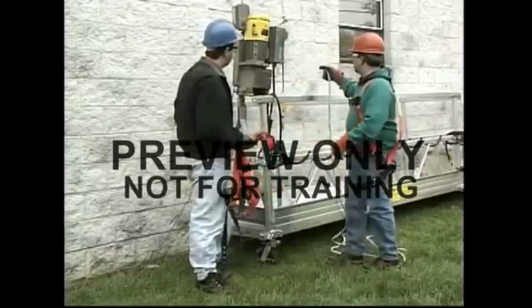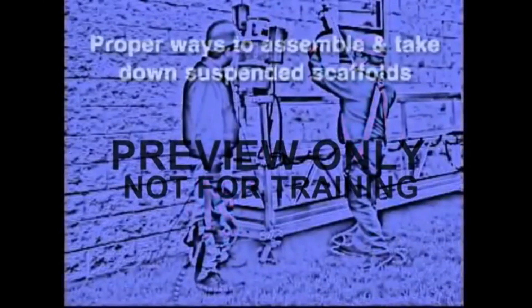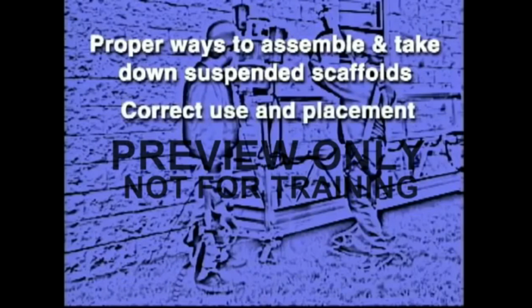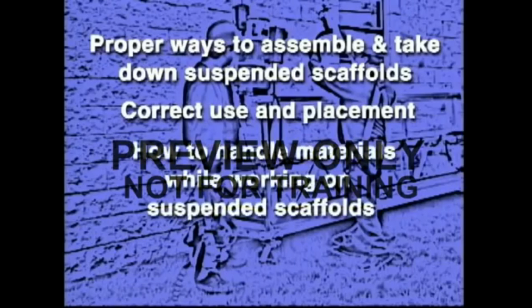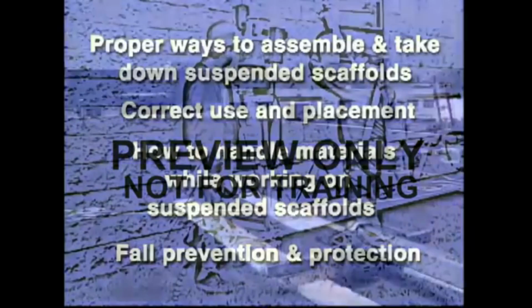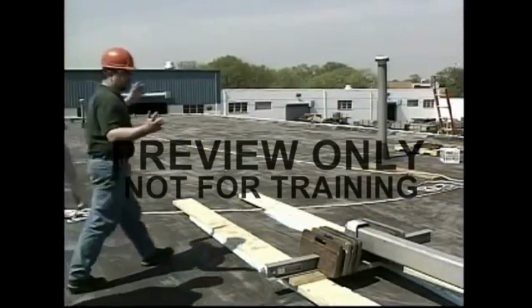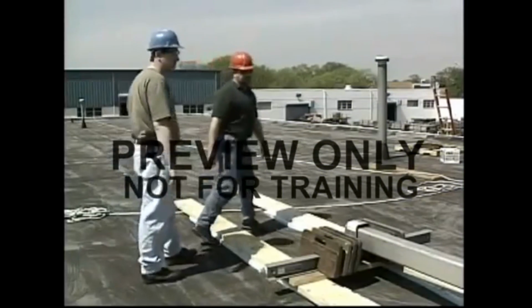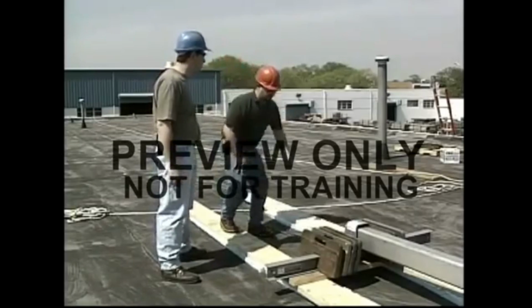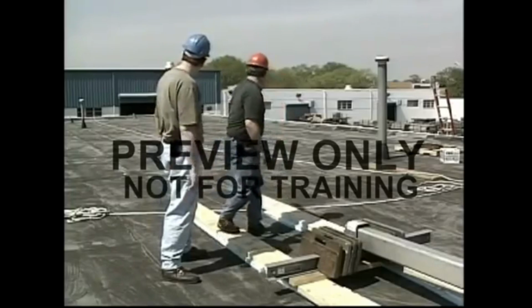OSHA mandates that this training include the proper ways to assemble and take down suspended scaffolds, their correct use and placement, how to handle materials while working on suspended scaffolds, and fall prevention and protection techniques. And even though workers must undergo this thorough training, OSHA also requires that a scaffold expert be on site at all times, whenever scaffolding is being used.